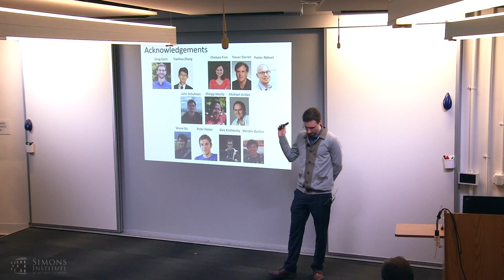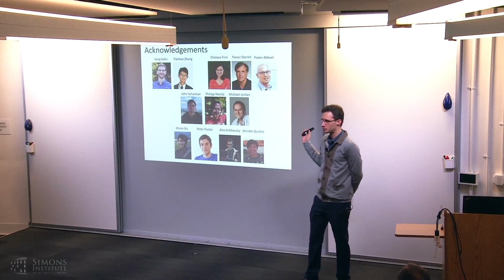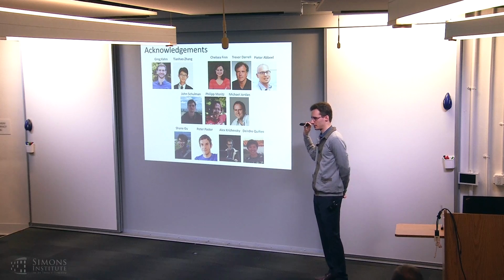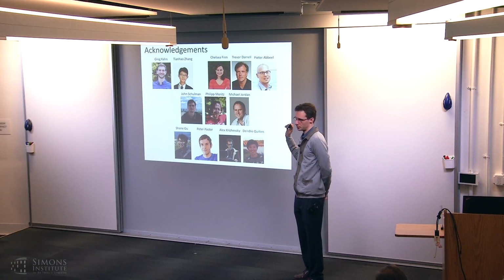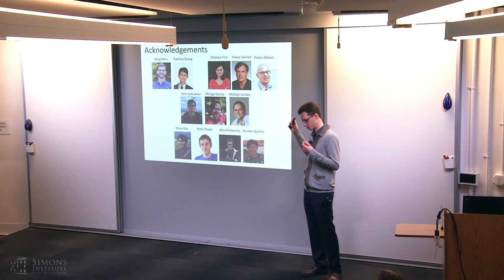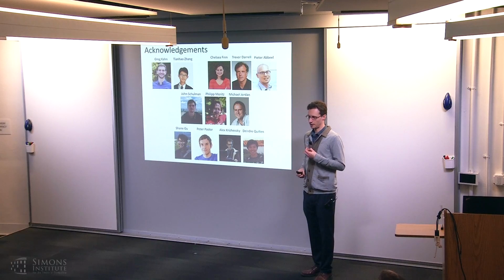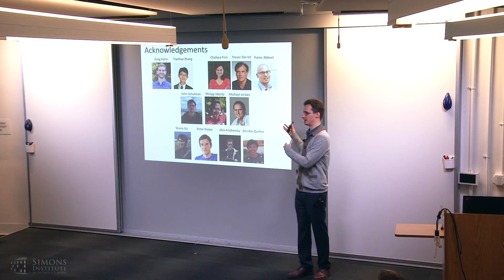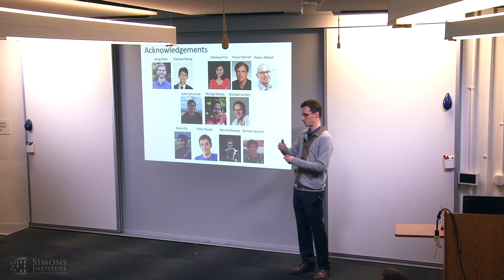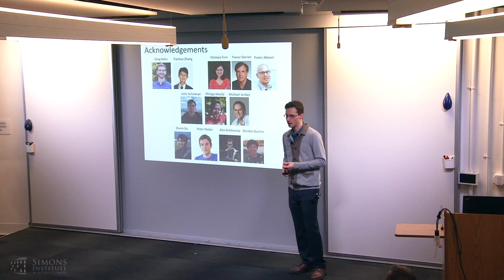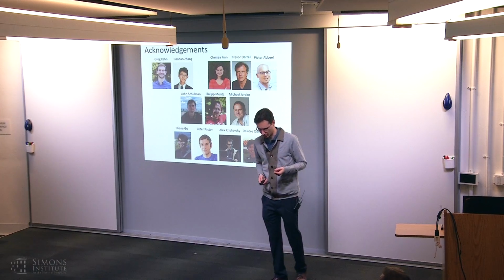And actually, if you remember the door opening task, part of the reason why we used the Q-learning based method for that is that it does quite a bit better in terms of exploration than the model fitting approach. In that case it was just random exploration using that Boltzmann style thing. But if it accidentally experiences one success, it'll pick up on that and then reinforce it further. With the model-based approach, all you get out of it depends on how good your model is. So if you get one success and like 9 failures and you fit a model to it, you won't necessarily visit that successful region over and over again. But doing things more explicitly with exploration can go a long way.